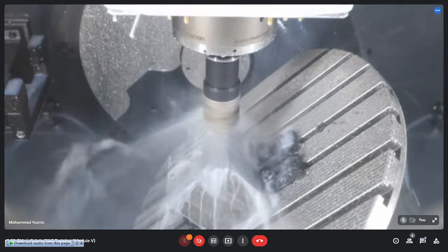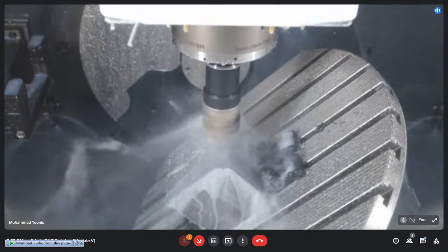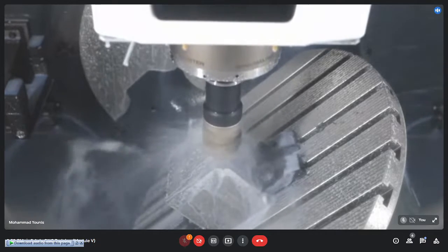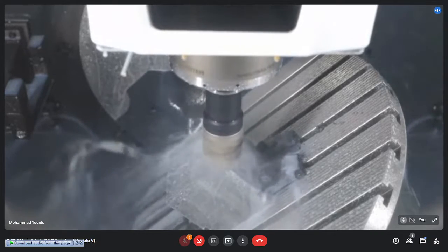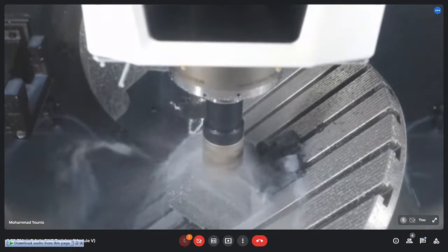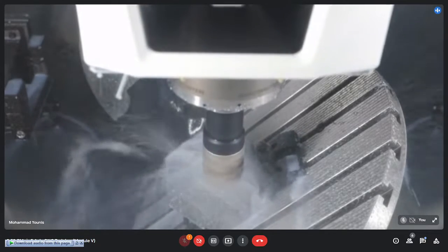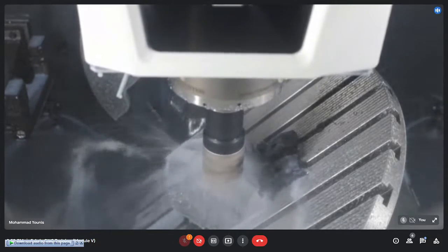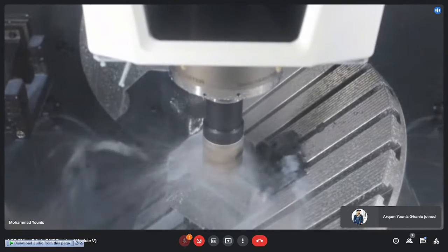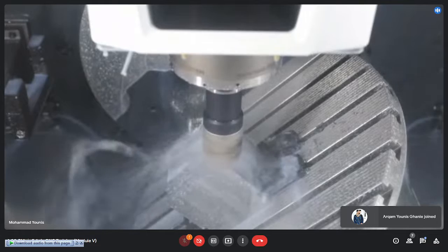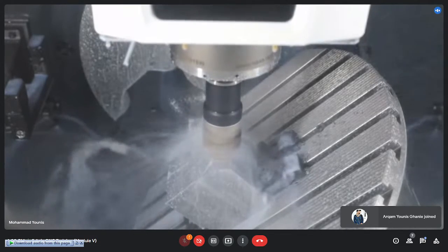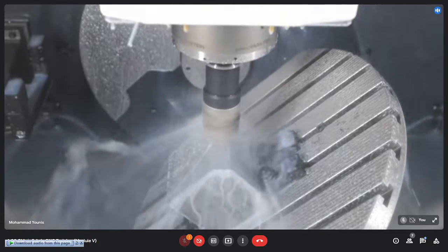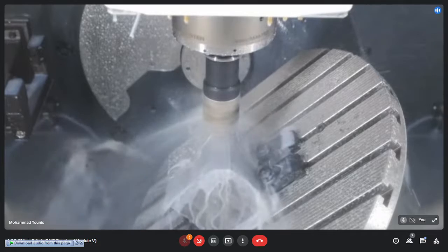So we can't do this chamfer milling on 3 axes, because on 3 axes, if we want to do this chamfer milling, we need to unclamp the workpiece again after we finish the machining on the top surface. Then we have to clamp it again at this particular angle. We need to set it manually, and there is a chance that we will get lower precision. But here the machine is actually setting these angles.